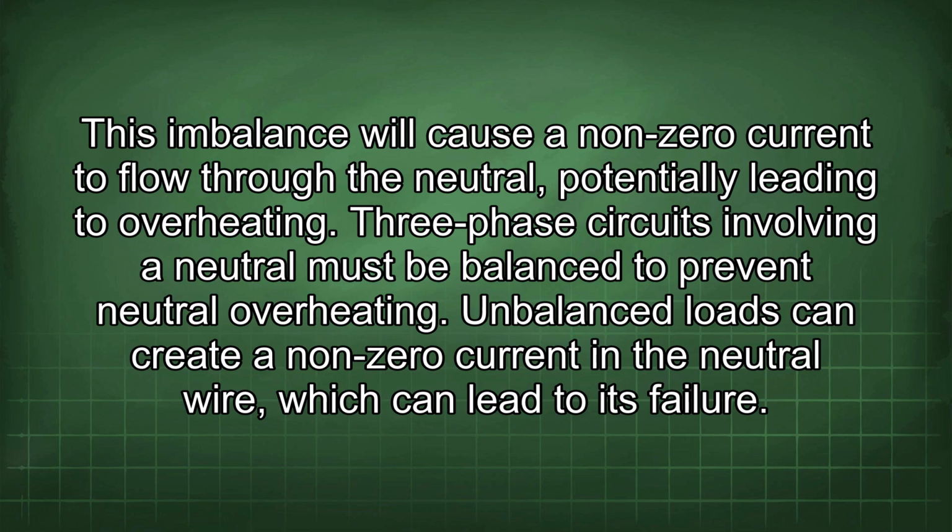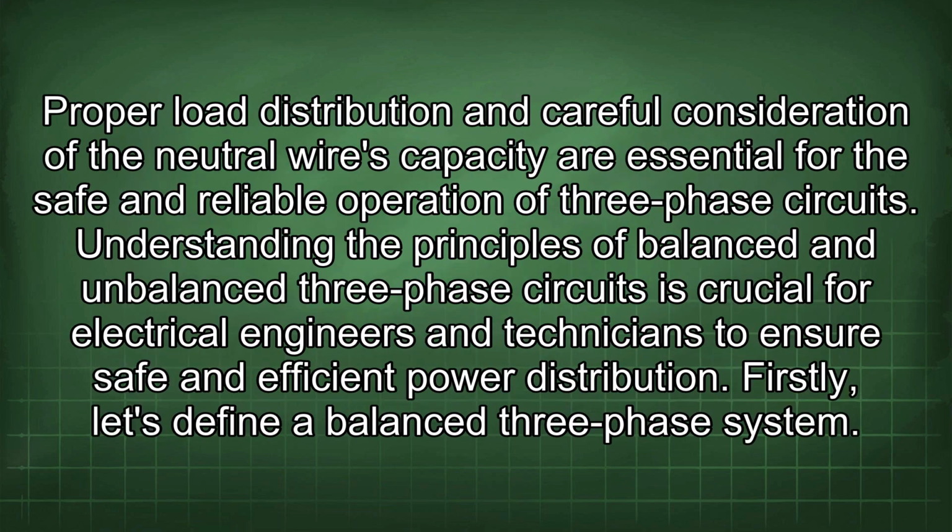Three-phase circuits involving a neutral must be balanced to prevent neutral overheating. Unbalanced loads can create a non-zero current in the neutral wire, which can lead to its failure. Proper load distribution and careful consideration of the neutral wire's capacity are essential for the safe and reliable operation of three-phase circuits. Understanding the principles of balanced and unbalanced three-phase circuits is crucial for electrical engineers and technicians to ensure safe and efficient power distribution.